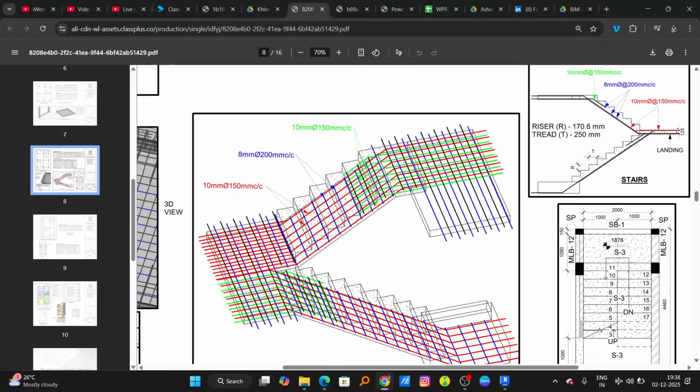The only thing he did was highlight this particular rebar with different color codings like blue, red, green or yellow, or whichever color you want to use, and then hide the staircase, or actually make a transparency on the staircase and make it a hidden element.